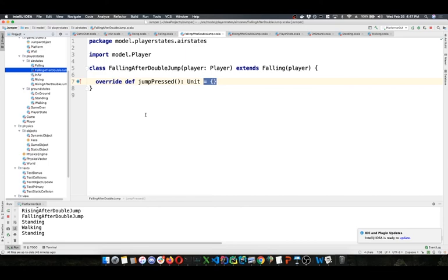And then at some point, you're going to have a button that changes the functionality, and you have this state that has identical functionality of a state that you've already written. Well, you just transition back to this state, and now you can start closing in your state diagram and start finishing up your design and wrapping things up to be able to complete your state diagram and your design of that. Once you start getting those states that are already existing and you're traveling back to them, you get your whole state diagram. Then, and only then, it's time to start actually coding and implementing those states.